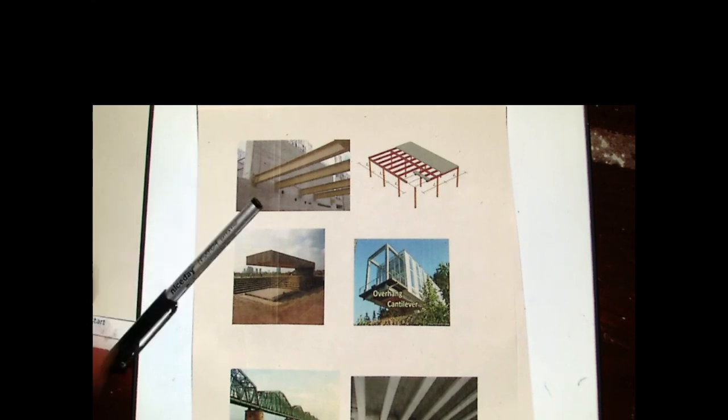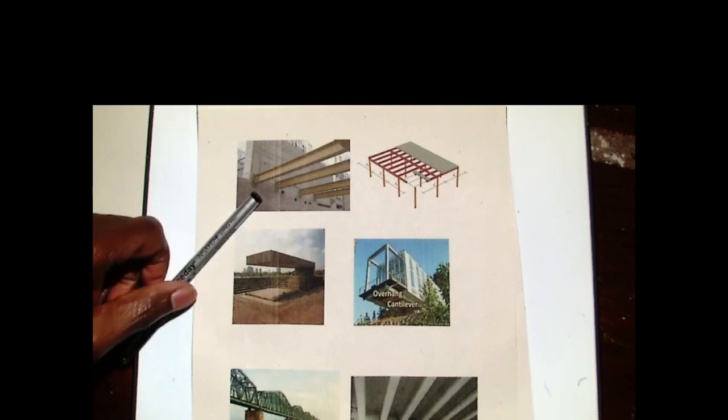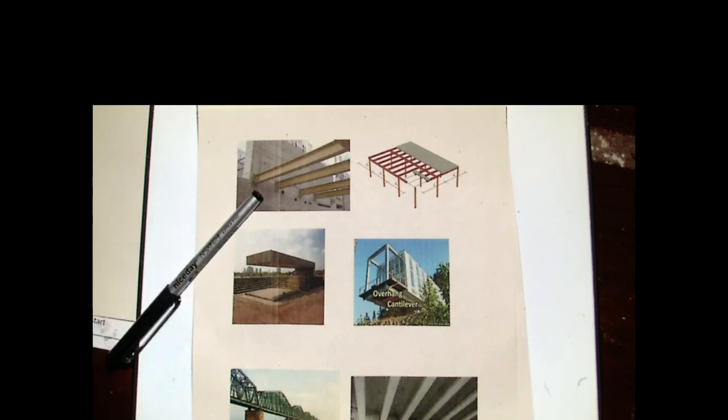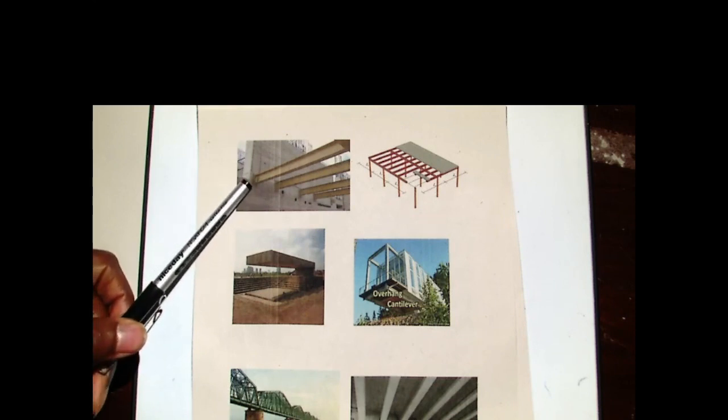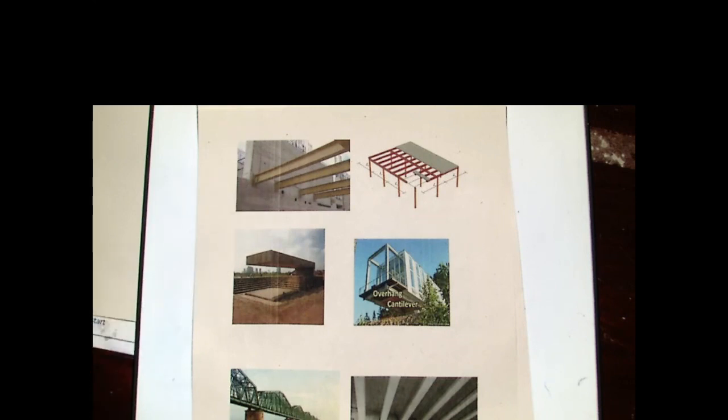I'm sure you've seen structures like that, a beam within a civil engineering structure there to provide support, supported by a pin connection at the end. So that is going to take some load. What we were trying to do last week and also this week is, once the loads are put on that beam, make sure that the magnitude of the stress developed is not too high, that it will break the beam. And you don't want the beam to have a very large deflection.